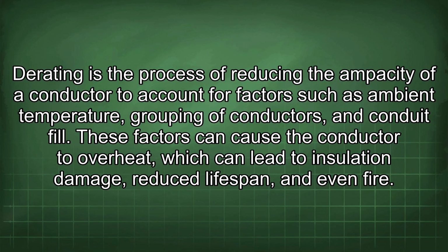Derating is the process of reducing the ampacity of a conductor to account for factors such as ambient temperature, grouping of conductors, and conduit fill. These factors can cause the conductor to overheat, which can lead to insulation damage, reduced lifespan, and even fire.